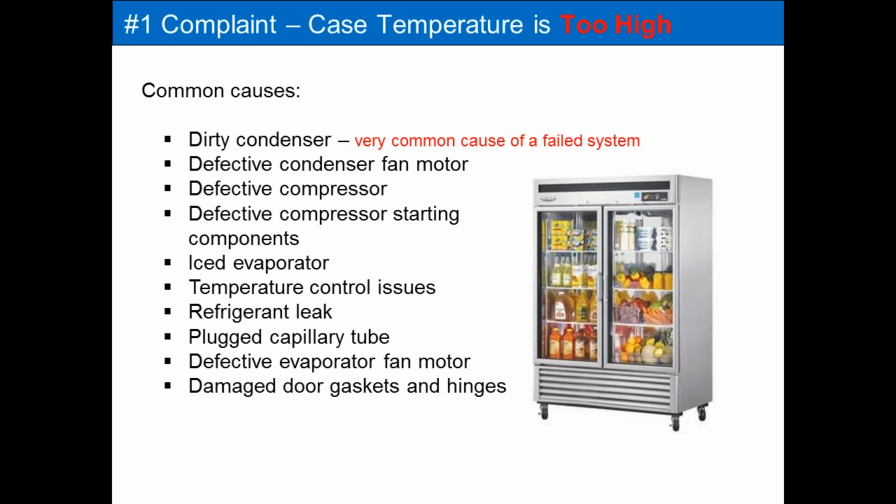So let's get into troubleshooting. And the number one reason for you being out there is going to be the case temperature is too high, right? You're going to get a call from a customer saying, hey, my case is too high, the health department was just in here and it's supposed to read less than 41, let's say, and it's reading 45, or it's at 50 or 60 degrees. That's a pretty common call.